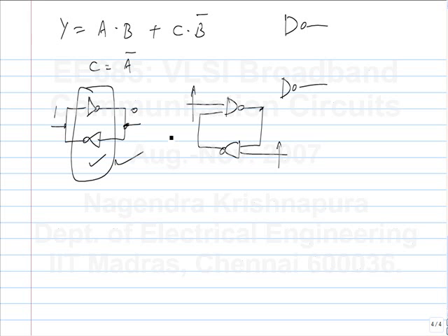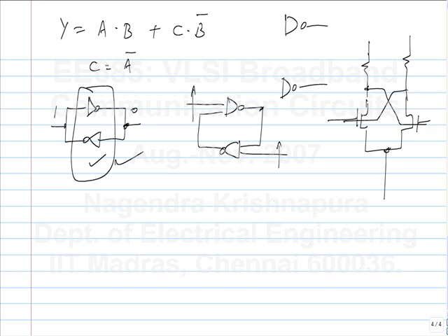In CML, you can get a positive feedback simply by inverting the wires. If you had CMOS inverters, you would have needed 2 gates to invert it and make it positive feedback. In the case of a CML gate, this function can be realized by doing this. So let's say this side is the lower side and this side is the higher side. That higher gate voltage makes sure that all of the current flows here, and this side will remain the lower side. So that is a positive feedback latch. Because you have both the inverting and non-inverting output available, you don't need 2 separate gates.